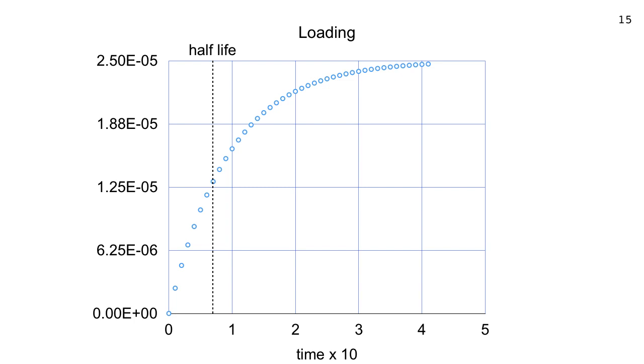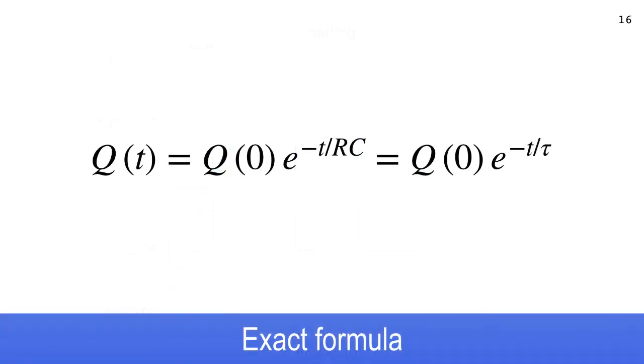All right, it'll oppose further loading, but it asymptotically gets to the maximum load, just like a charging capacitor loading up. Now, remember this. Here's something I want to point out to you. All these circuits with R's and C's and L's and RL's and LC's, they're either exponentials or they're sines and cosines. All right? And there's a reason for that. I'm going to go over the reason for that with you in the next few slides.